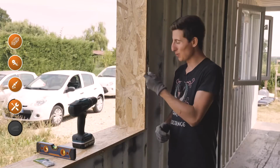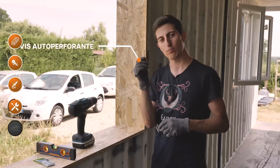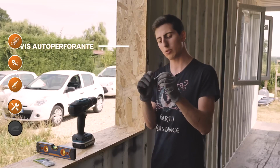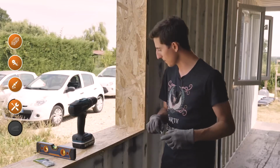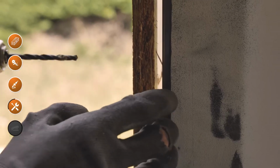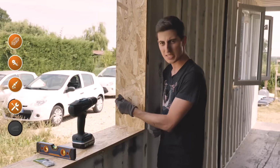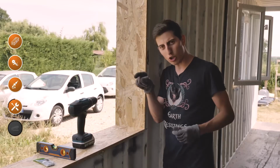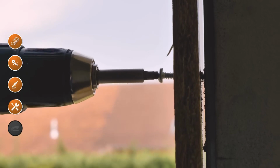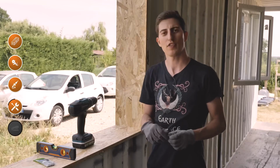Well, I'm going to have to screw it to my reinforcement tubes. And for that, I'm going to use self-drilling screws for steel, 45 millimeters long, 5.5 in diameter. I'll pre-drill my oriented strand board at 5.5 and my steel tube at 4.5. The goal is for my screw to go easily through the oriented strand board, anchor itself in the steel, and pull the oriented strand board tight against the tube. I'm going to put 3 on the right, 3 on the left, and that'll do it.